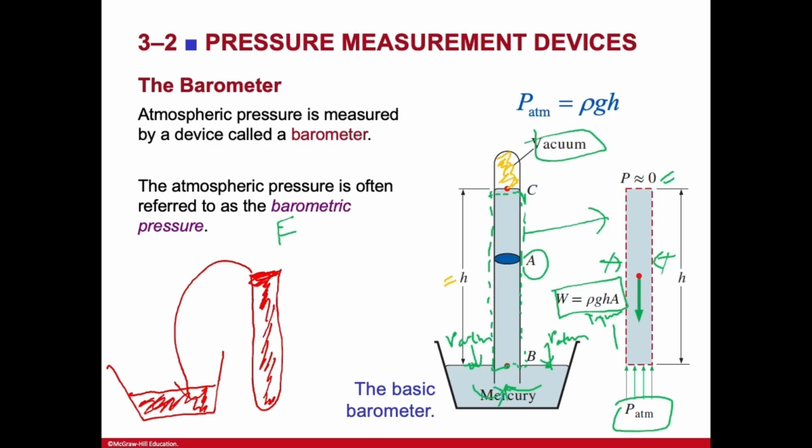since the fluid is stationary, let's start with what the net force is. The net force will be P atmosphere on the bottom acting upwards times the cross-sectional area, because it's positive. There is no force on the top surface, and the final force will be weight.